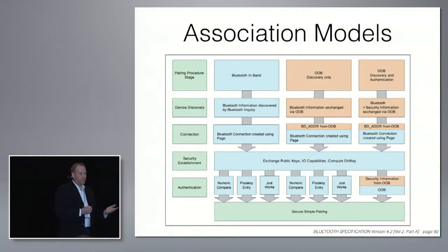Then they switch to the paging channel. Then there is a paging request, and then a directed paging response based off of that device access code back from the master. Once that's all worked out, they get into a connected state.